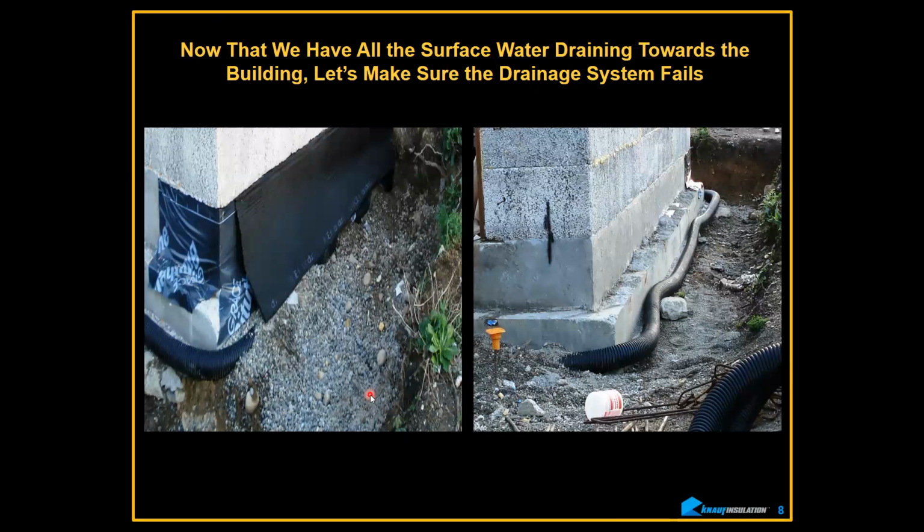Here are details that are highly problematic. Just bring your attention to a couple of things. This block is called Rastra block. I don't even know if it's still made anymore. Highly porous, nothing more than styrene prill aggregate in a cement base, very porous, low R value, even though they said it was somewhere on the moon for R value, and it's not. That's just a sidebar there. I don't recommend it except in the desert, if it's even still around.